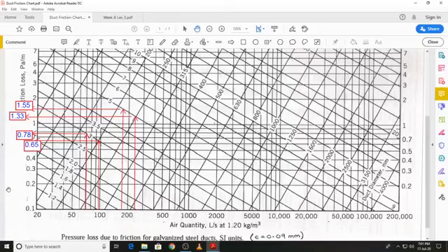And we now have the desired pressure drops per unit length for the first 4 segments. For segment 5 it is the same as for segment 3. We will return back to the solution. With these values we have got the complete table. The only thing that was missing was the pressure drop per unit length. And we can now begin calculating the pressure drops in the various runs.